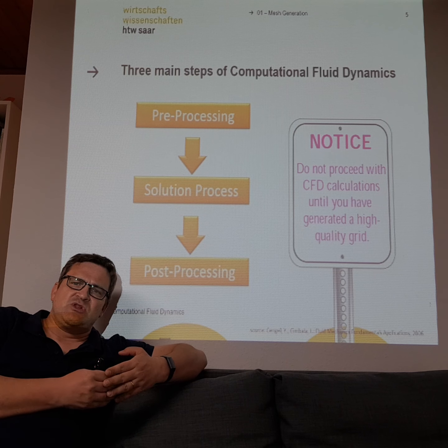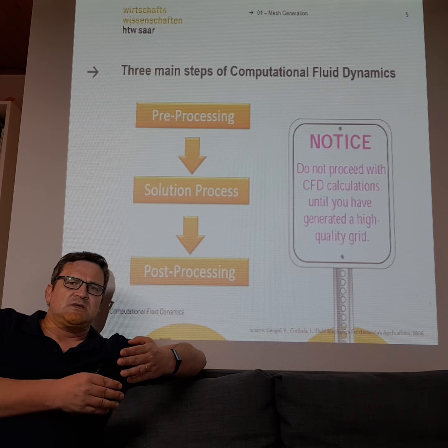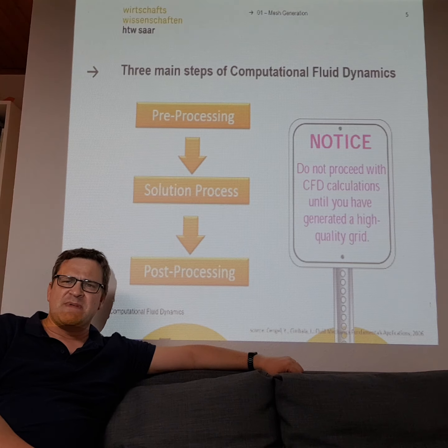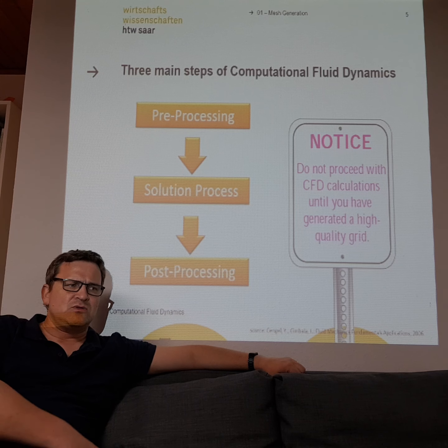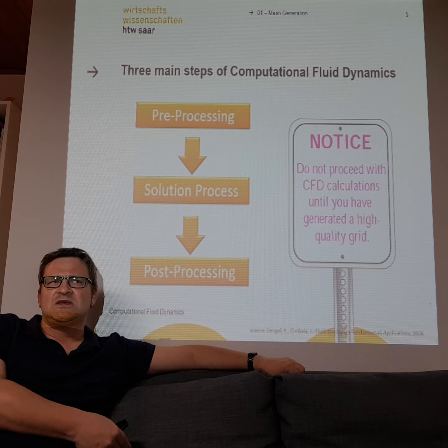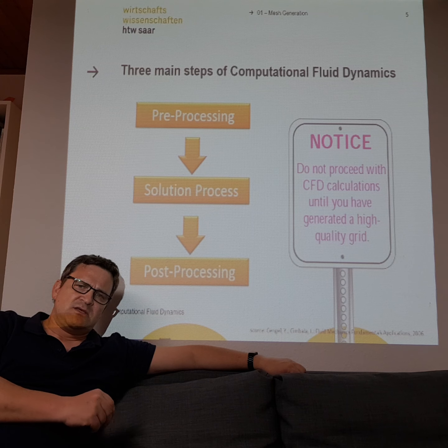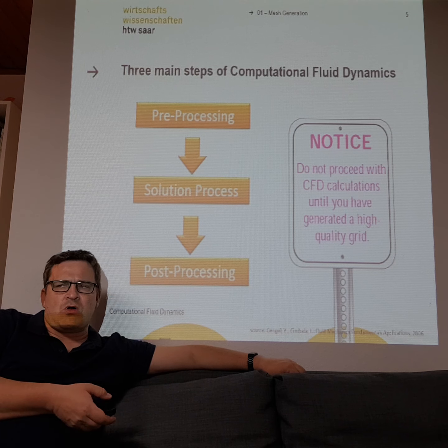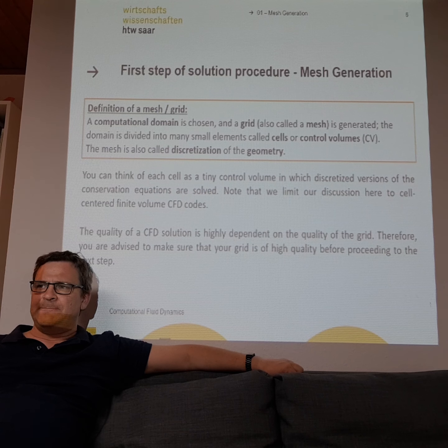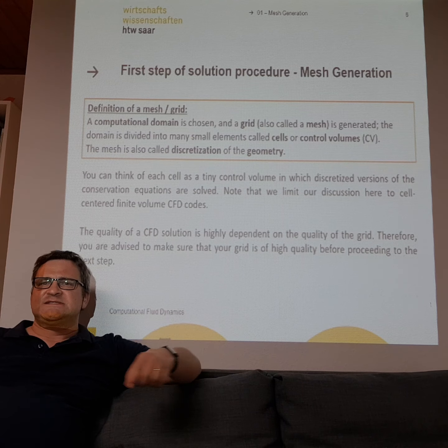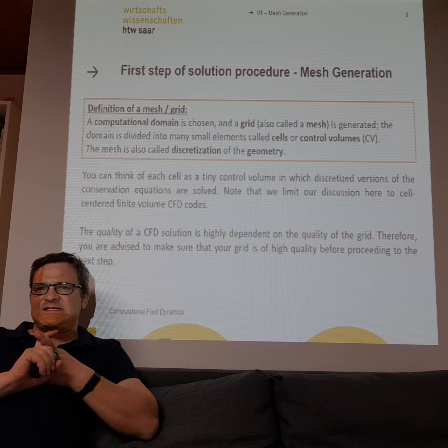The simulation always depends on the mesh quality. If you start with a bad mesh at the beginning, everything will be of bad quality, and also the results will be wrong. So the first step of the solution process is our mesh generation, and that's like an art.